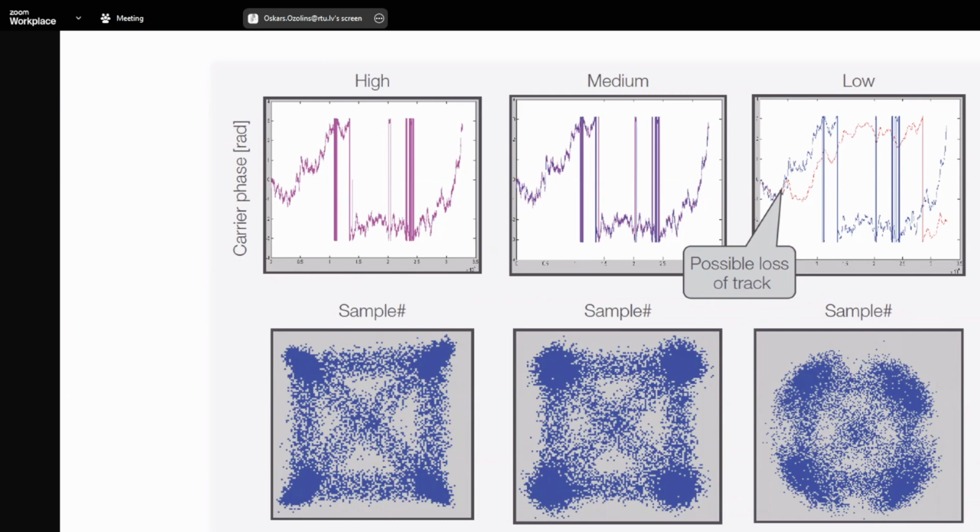Here we also need to know what has been done with digital signal processing. So here's like overcompensation of the phase noise, because what happens is that you need to do rotation of this constellation. And when you see the constellation points, these are just transitions for QPSK. What we are more interested in is these parts. So this signal doesn't look round, it looks oval, which means that in this direction, which is the phase direction, we have more compression.